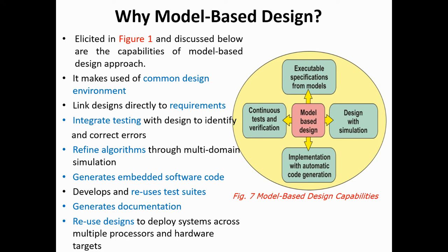Out of the requirements given to you, you can actually create an executable specification out of the model. We can integrate testing with design to identify and correct errors. So as you can see, we can create a test bench so that we can check whether our outputs are within the requirements, following the input combinations, following our truth table.